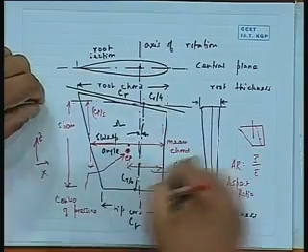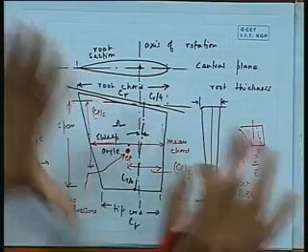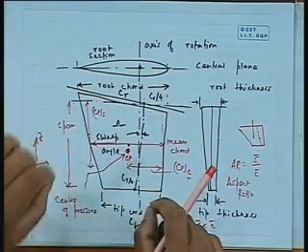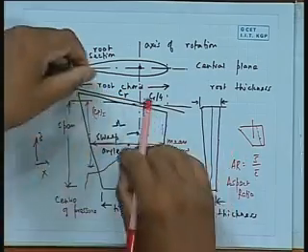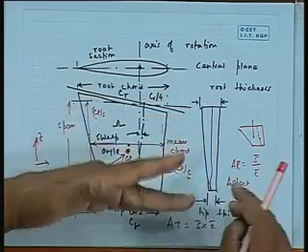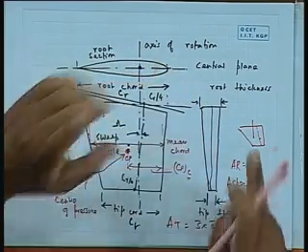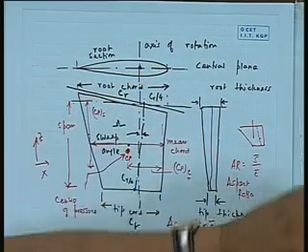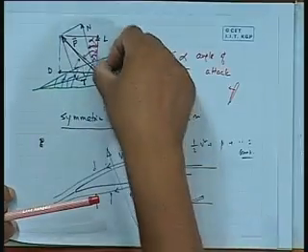On the other hand, there are some empirical formulas that have been found when you have these parameters known: length, breadth, mean chord, mean point, etc. You can estimate the total force, the overall CL, not for an individual section. CL means the net force coming on the rudder if you have turned it, because after the turning the angle of attack is going to be the same. Whichever section you take, the angle of attack is the same, so those directions are going to be the same.